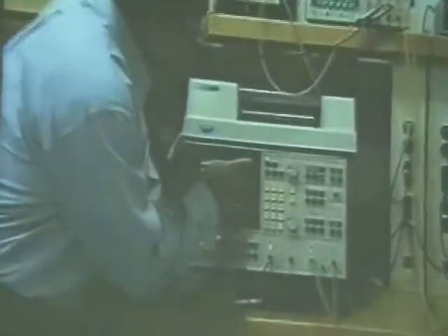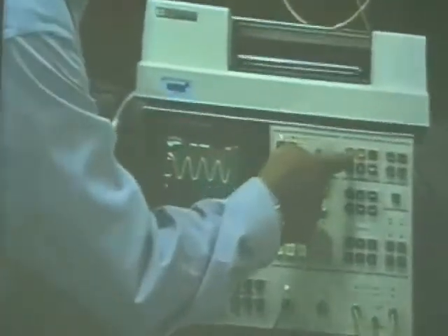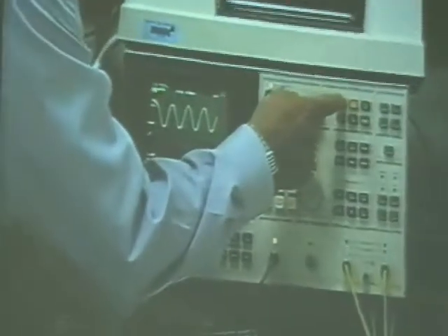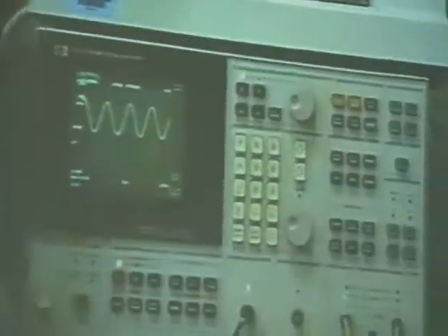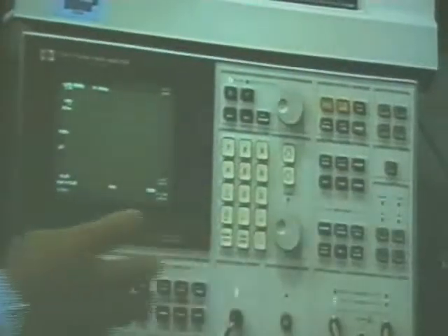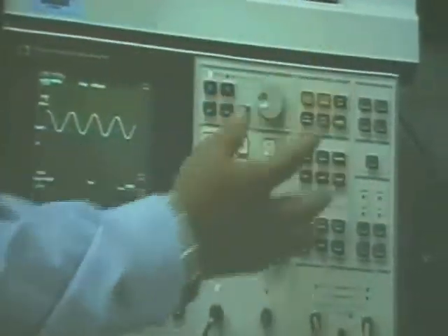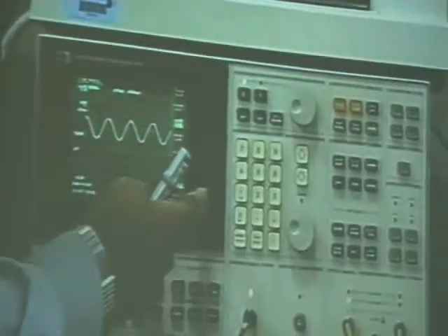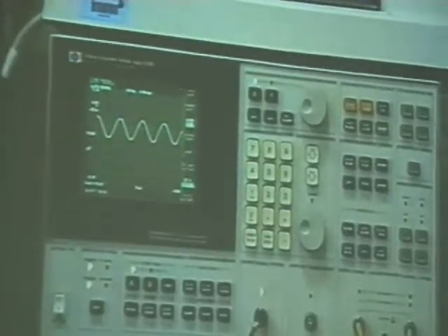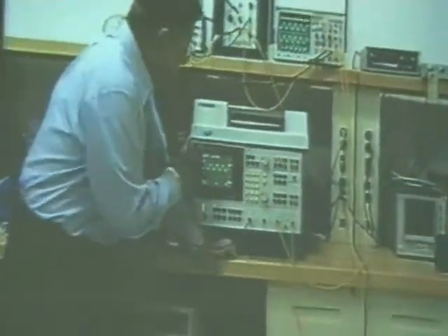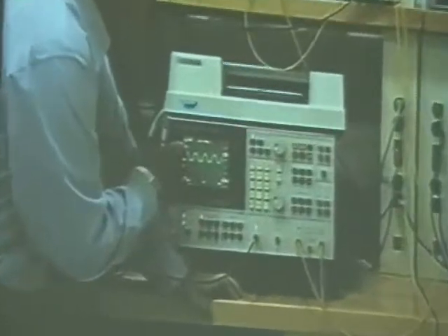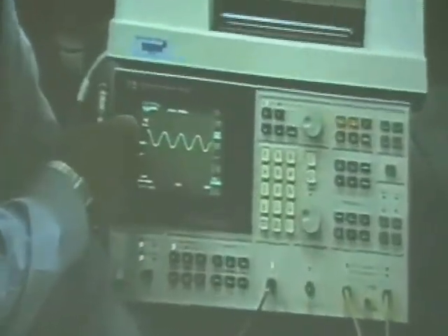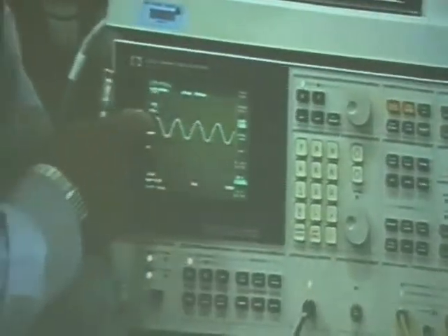As I did already here, I did the autocorrelation function, and now I'm going to take a measurement. So I'm going to push the start button. I didn't really explain what this does. This sets up the type of measurement. Right now, this measurement is for channel 1. Channel 1 is the signature coming out of this box A. So as you see here, this is the autocorrelation function for the sine wave.